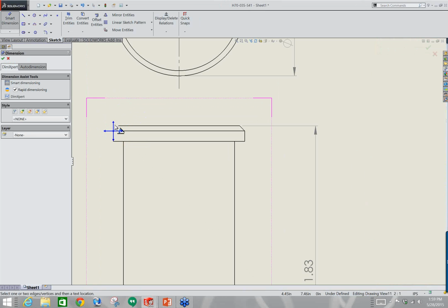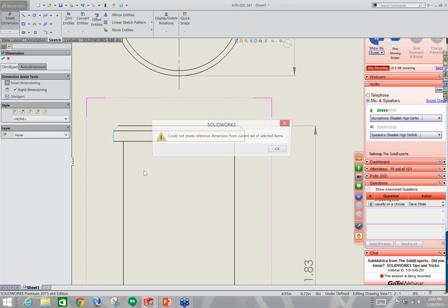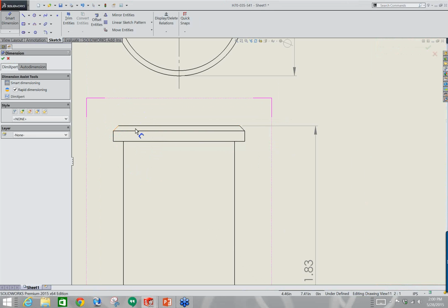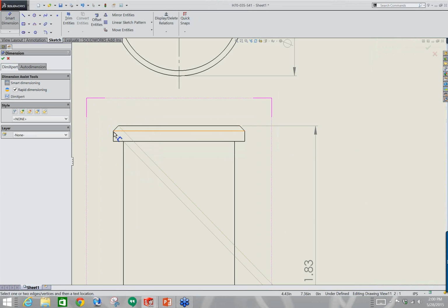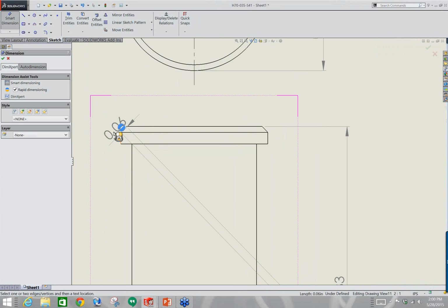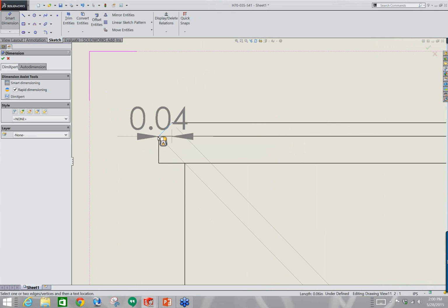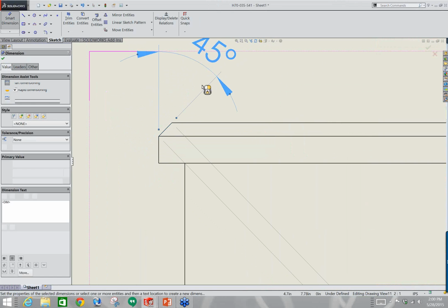Yeah, if I'm picking an angular thing like this, if I pick a point at the end of it, I can choose by this little triad what direction I want to make the dimension go into, right? So I wasn't going to pick that one, but I pick this vertex. Oops. All right, do it again. Again, here where I can grab that corner. There it is. And I can pick this direction and place it automatically.